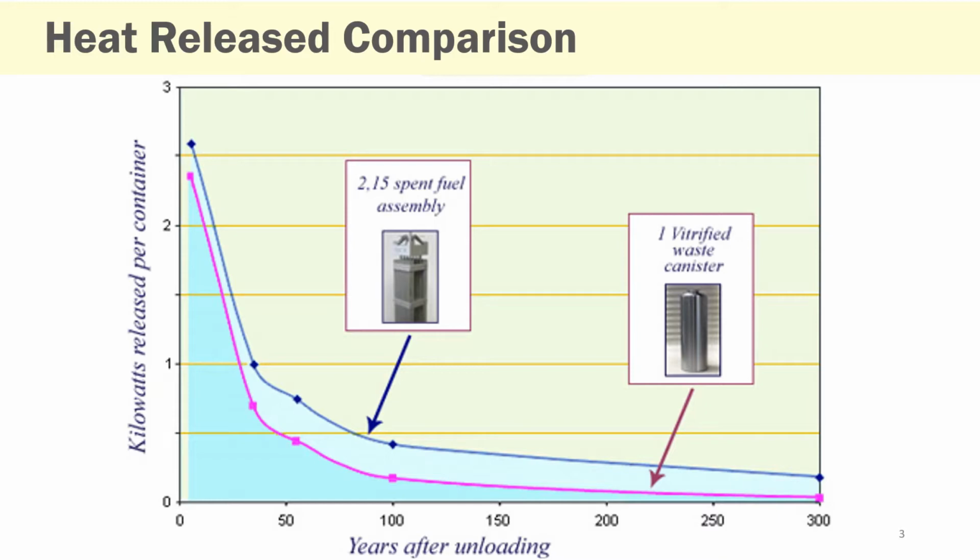Removing the plutonium significantly reduces the heat release, by about 30% after 35 years and 60% after 100 years. And remember, in the graph from the previous section, the long-lived actinides are the dominant heat generator. So if you remove the plutonium beforehand, that's going to go way down in the long term. Removing the plutonium would also enable smaller disposal facilities to be used. For reference, it takes about 1 kilowatt over an hour to boil 1 kilogram of water.